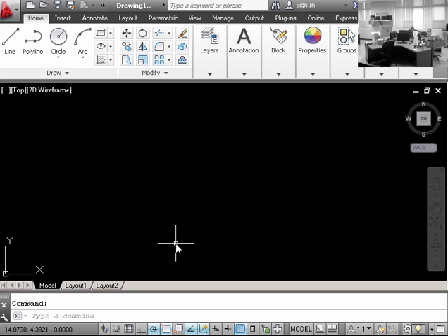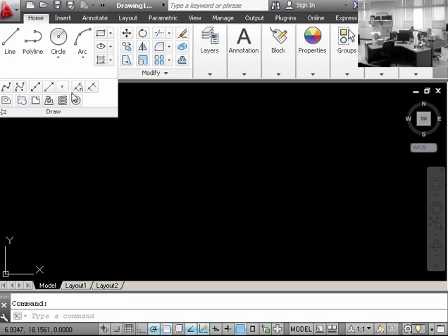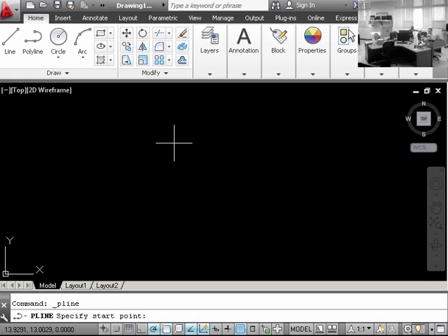Okay, so this section is all about what occurs right in this zone right here. This panel has all of the other stuff you can draw: polylines, circles, arcs, construction lines, clouds, those kinds of things. Now, the line command is used for most everything that you do, but one of the other ones that you use a whole lot, and it's easy to learn, is the polyline. The polyline is used very much in CNC applications and also 3D modeling.